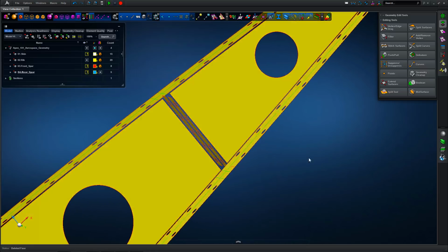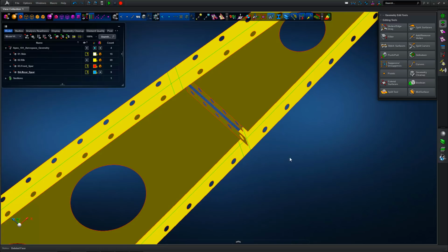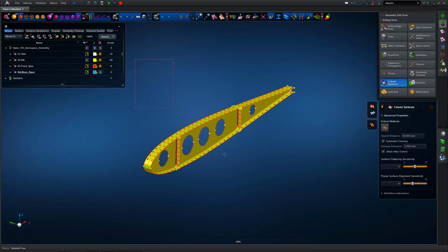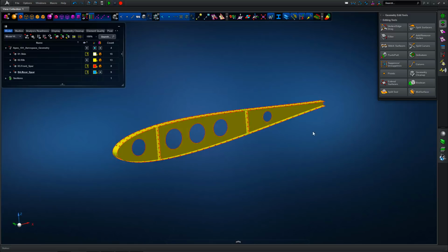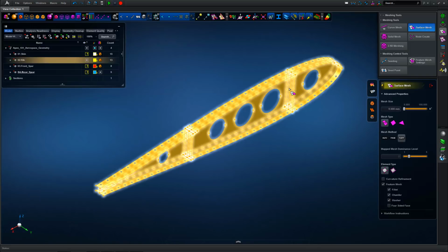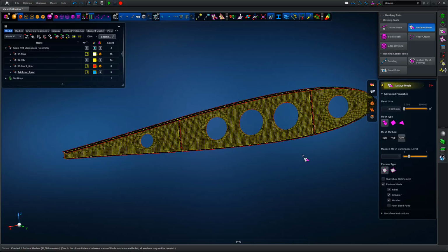So we're going to effectively repeat the same operation for a rib, just running through very quickly. A lot of the direct modeling tools within Apex make geometry to mesh or CAD to mesh almost a trivial operation these days, but we can very quickly mid-surface and extend those surface edges to meet adjacent surfaces to have one consistent surface definition.